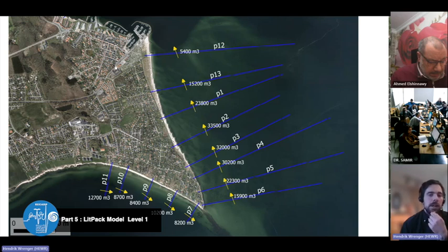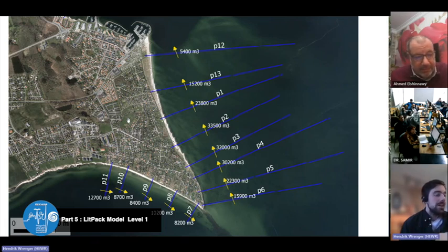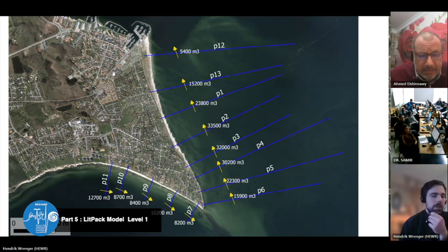That's the one reason. The other reason is the huge amount of small structures here. For every single structure here, the longshore transport doesn't re-establish anymore. So if you wanted to model this in a coastline evolution model, you would have to somehow include the effect of these as a longshore structure, like some form of revetment. But then what parameters do you choose? Basically, we pretty soon decided that we're too little in control of the output of what would come out of a coastline evolution model.